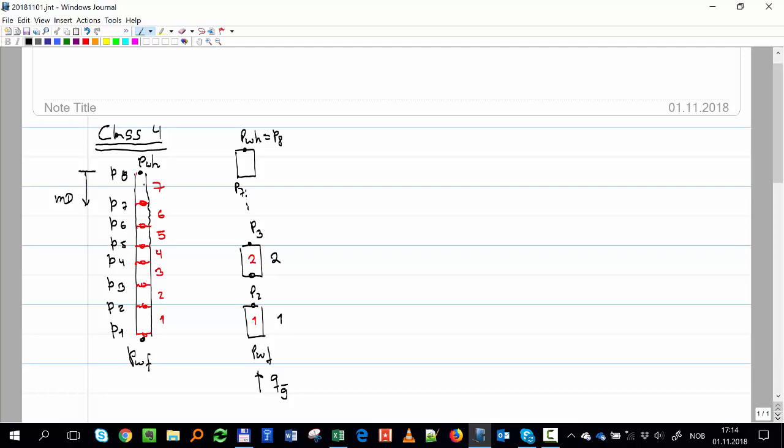And so forth. So what I have done is divide and conquer, what the Romans did a long time ago. I have a big tubing, I have an equation to solve that big tubing, but I'm going to cut it into a lot of small tubings, and I'm going to apply the same equation to each one of these small tubings. And I have to start from the boundary where I know the pressure. In that case, I know the pressure at PWH, so I'm going to move down to calculate P7, then with P7, I go to the next segment, I calculate P6, I calculate P5, and so forth.